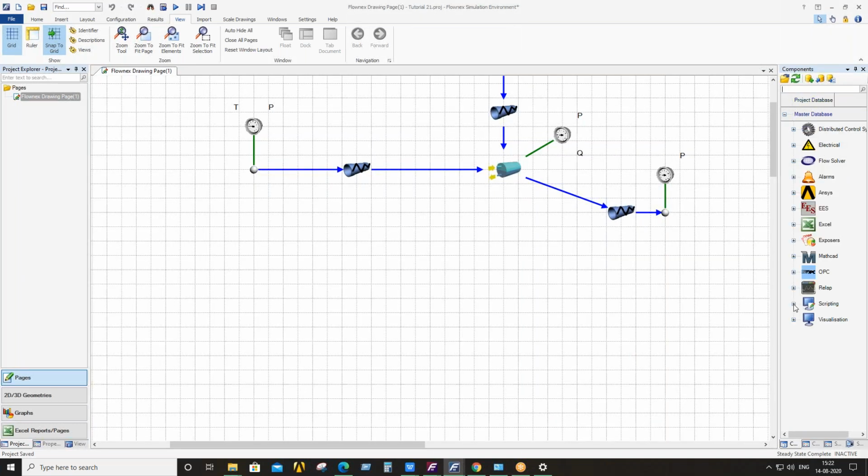Here you can see one element is there, Script. It is written in the C# language. So you can specify, but you need some programming skill. You can put in your own formula, so that you can calculate your hydro turbine parameters within this environment. So it is possible, but at this stage there are no such components with which you can simulate a hydroelectric power plant. Basically, this is designed for thermal design cycles. Direct provision for that cycle is not there, so in an indirect way you can write down your formulas and then do the calculation accordingly.